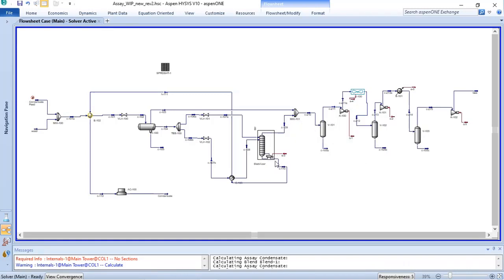So in the bottom we have our waste, and it is hot. You can see that it is 155 Celsius degrees, and because of that he used a heat exchanger to preheat the liquid from 38 degrees Celsius to 60 degrees Celsius, and the return in the waste he used it also to do the pre-heating of the raw material at the plant inlet or at the battery limit.